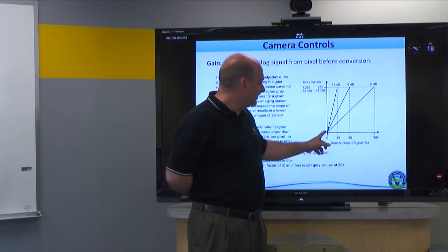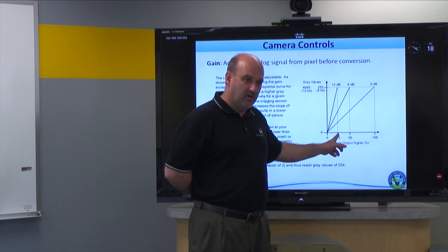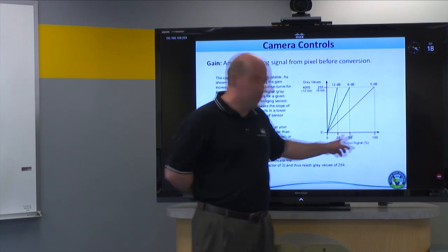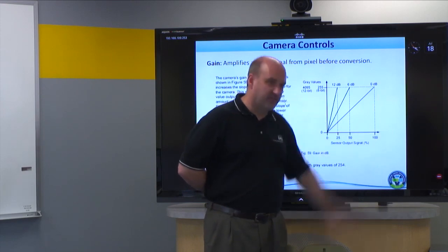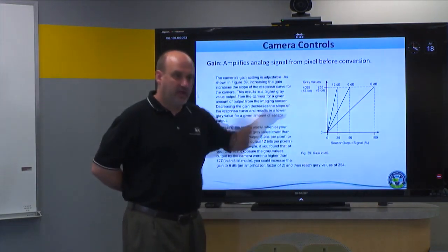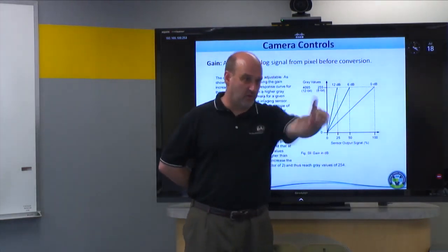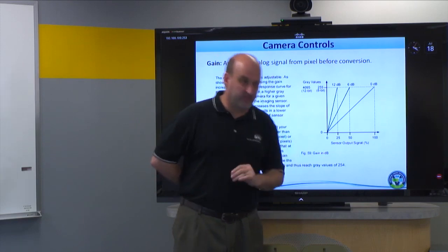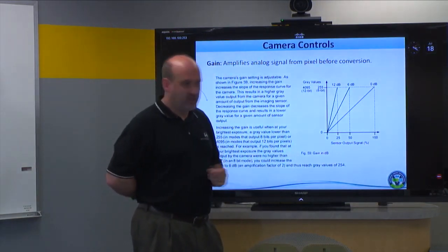But what's basically happening is in a low light situation, I'm only filling that well up 25% of what it would be in a bright light situation. So in sunlight, I get enough photons that the 40,000 electron well is completely full, and then I can run a minimum amount of gain, 0 dB of gain, and get a full output out of that and see my image. Great imaging. But truth is, very seldom are we in those cases.